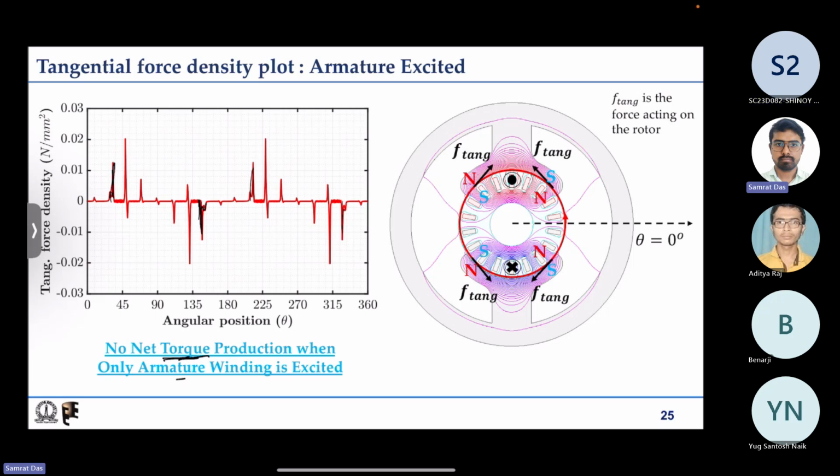It can only be done by drawing a circle along the air gap and getting the B vectors and their components; that is the only way. Analytically that is not possible. Tangential H also will be there, sir. Yes, because B is there, tangential H will also be there, but that is very difficult to get. Okay, sir.